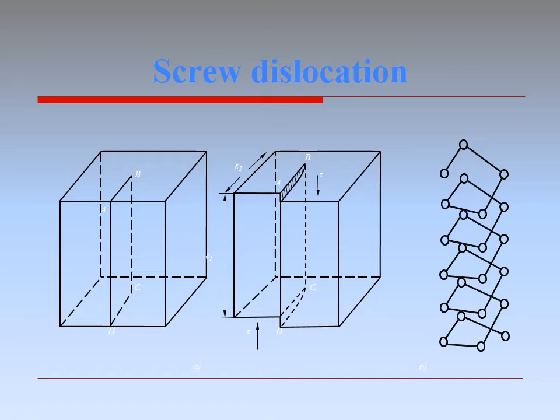Since the incision ABCD only reaches the middle of the crystal, the right part cannot move entirely towards the left by one lattice period. The displacement of the right side towards the left decreases in the direction from point A to B. The top atomic plane is curved. Similarly, in the deformed second atomic plane from above, the first part of it from the front edge is shifted by one lattice period and merges with the third, and so on.